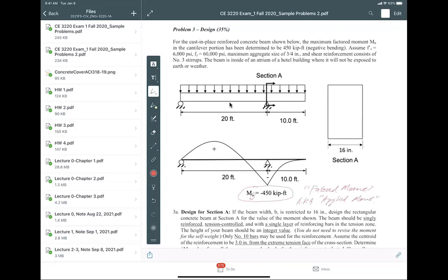Okay. So AKA required flexure strength. They're all the same thing, meaning Mu. You don't need to do any factorization anymore, just Mu. That is it, folks. So pay attention to that. Don't get confused and start calculating self-weight and all that. You don't have time.